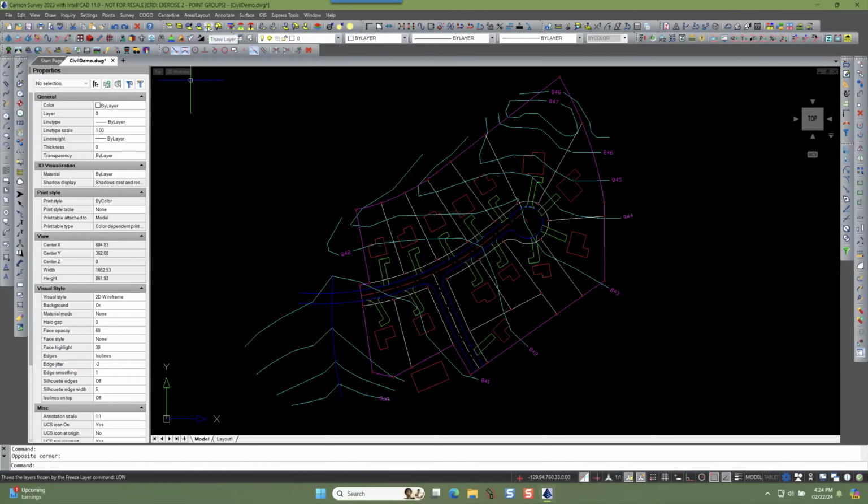And then I've got this one which says thaw a particular layer. If I do that, it's going to thaw the last one that I froze. So I'm going to go back and turn that back off. Or I've got this one that says thaw and turn on all layers. That does exactly what you think: it's as if you ran the layer manager, selected all your layers and thawed and turned them on so that everything is visible all at once. Okay. So that's one way of doing it.